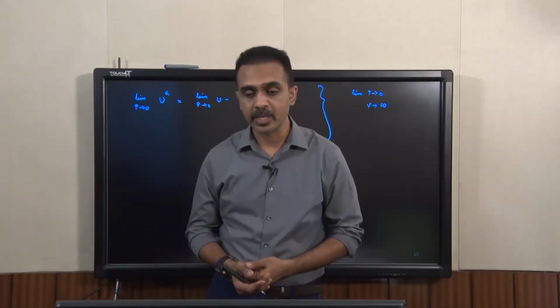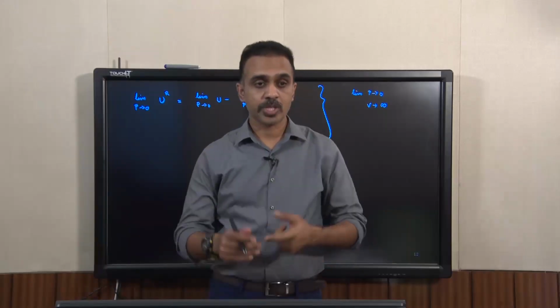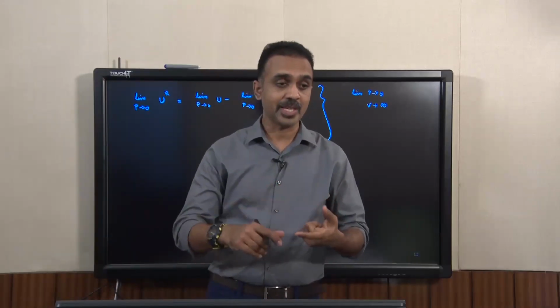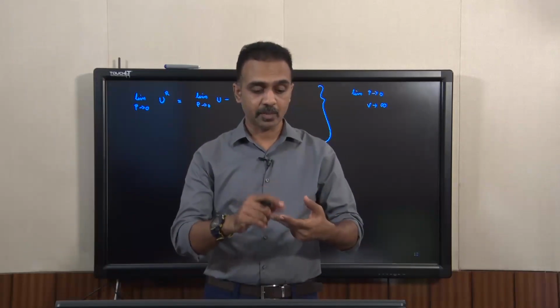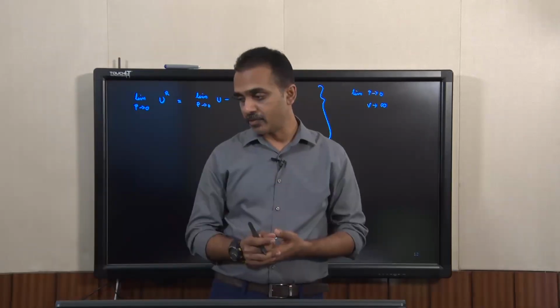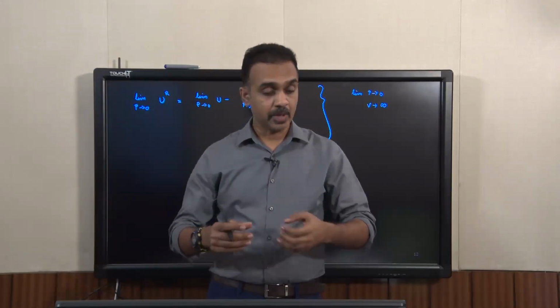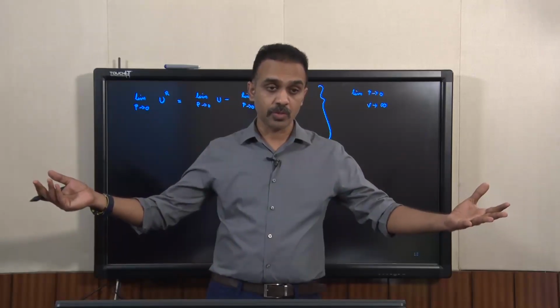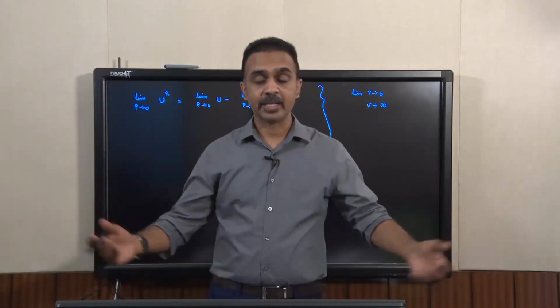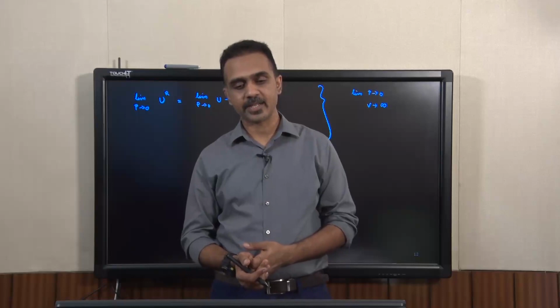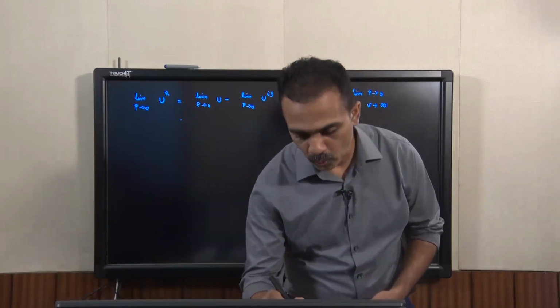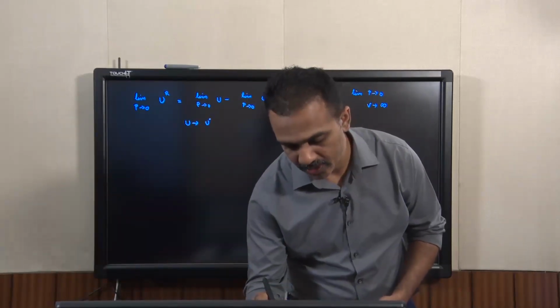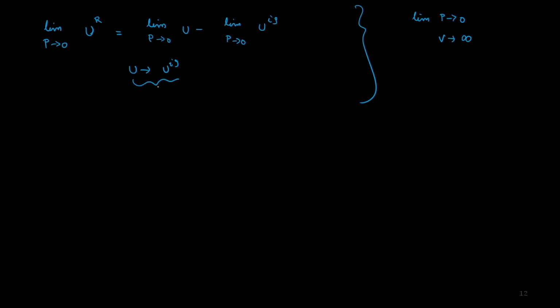And when that happens, the internal energy, which is a result of the molecular level kinetic, potential and other forms of energies, because the intermolecular forces go to 0, they exactly behave as if they are an ideal gas, and U will tend to go to U^ig at this limit, and so this U^R is going to go to 0, right?